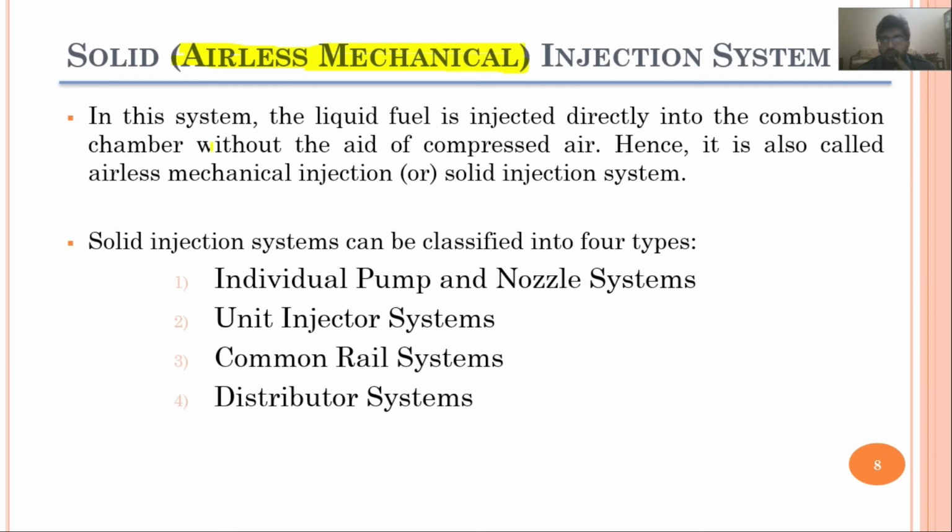In these systems, the fuel is directly injected into the combustion chamber, and this fuel is pressurized by using some high pressure pumps, and we are not using air for pressurizing the fuel. I hope the difference between the solid and air injection systems is quite clear.